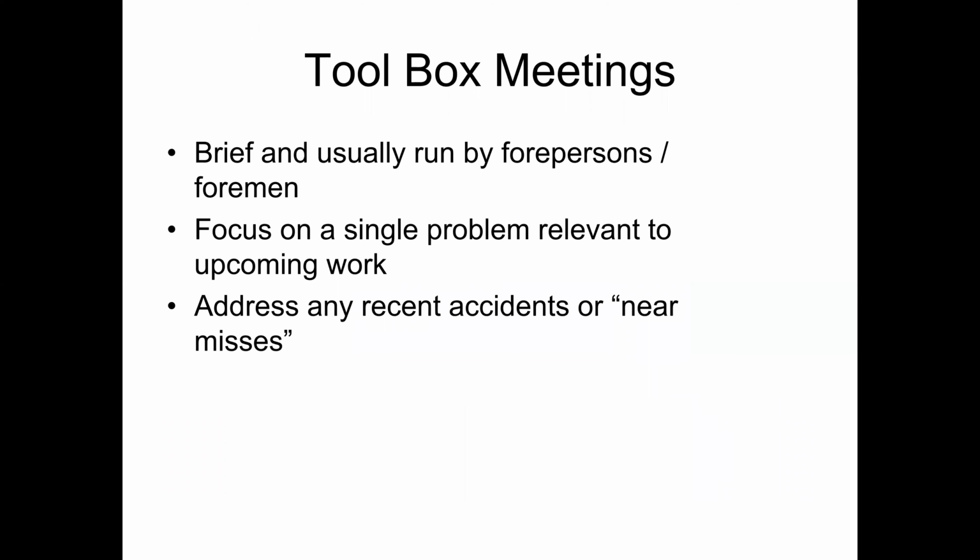Then the workforce should have toolbox meetings, or toolbox talks, before starting their work, a brief usually run by a person in charge of a crew of four men. The person in charge should brief the workforce on how to work safely in this two days of work, focusing on a single problem relevant to upcoming work. They should talk about what they are going to do today and how to do it in a safe way. Address any recent accident or near miss, or share others' experience, and motivate the crew members to work in a safe way. It's a small briefing before starting work in the morning. All the crew members stand, discuss, and share their safe work experience.